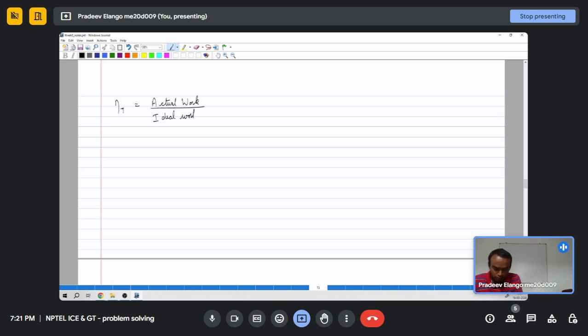So, if you draw in the TS diagram, we have two pressure ratios, and in case of isentropic expansion in turbine from 1 to 2, we would have a straight line like this, 1 to 2, right? But so this is called 2s, that is in isentropic expansion delta s is 0, but in actual we will have some increase in entropy. We will end up somewhere here, that is 2. This is pressure 1, this is pressure 2.